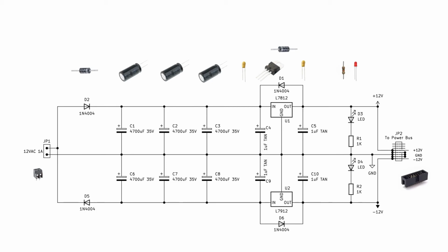A final note. I know that some Eurorack modules will need 5 volts, especially if they contain logic chips. I am building the modules myself, it is a DIY project, and I am planning to build mostly analog modules. I don't see the need to add the 5 volts to the power bus for my projects. If I do stumble upon a design that needs 5 volts, I will add it to the module's PCB and derive the 5 volts from the 12 volt supply.